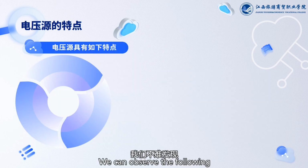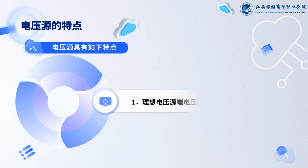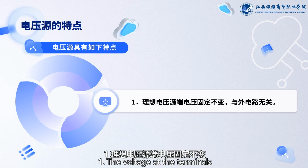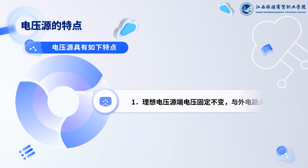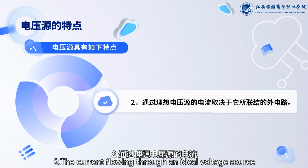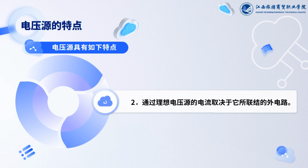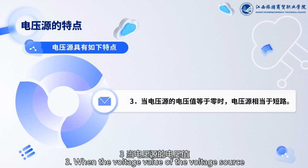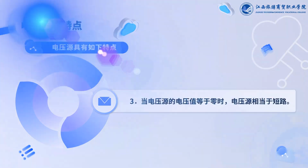We can observe the following characteristics of a voltage source. 1. The voltage at the terminals of an ideal voltage source remains fixed and unaffected by the external circuit. 2. The current flowing through an ideal voltage source depends on the external circuit to which it is connected. 3. When the voltage value of the voltage source is 0, it can be considered as a short circuit.